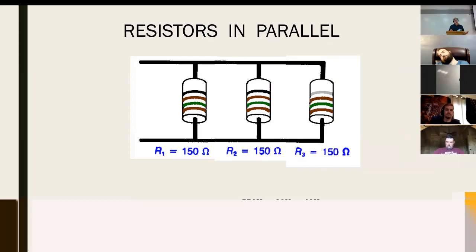I can use that method that we just went through with the inverse of conductances, but anytime you have resistors in parallel that are the same value, there's an easier way to do it, and that is to take the resistance of 1 and divide it by how many you have. So in this case, what would be the total resistance of this parallel network? 50, good, 50.